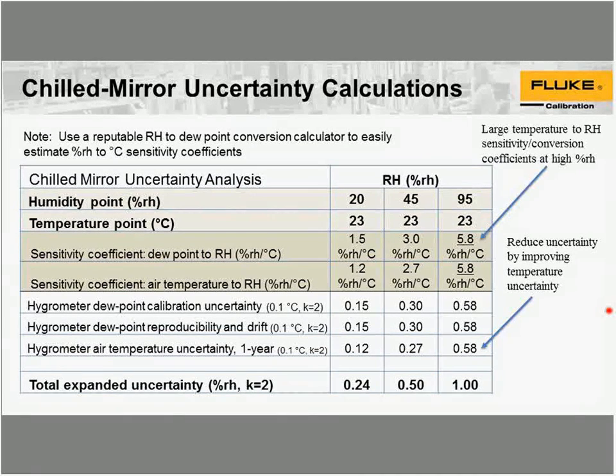Interesting to see how things evolve. I've seen that humidity does act that way. You get slightly different results depending on the temperature that you're measuring at. So don't just assume that because it works well at 23 degrees C or 25 degrees C, it's going to work well at 20 or 18 or some other temperature.